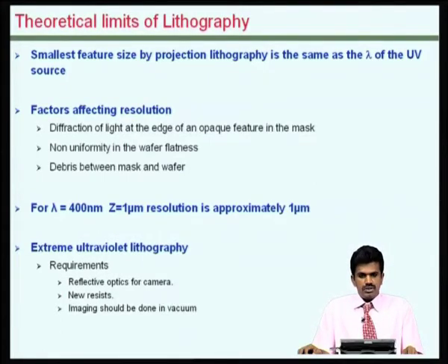Whereas, as I have mentioned earlier, it is possible to get about 1 to 2 micron in a typical lithography process used for building microsystems. This is done by extending the lithography technique, accurately controlling various parameters used in the exposure, as well as in creating the thin film of the resist and things like that.